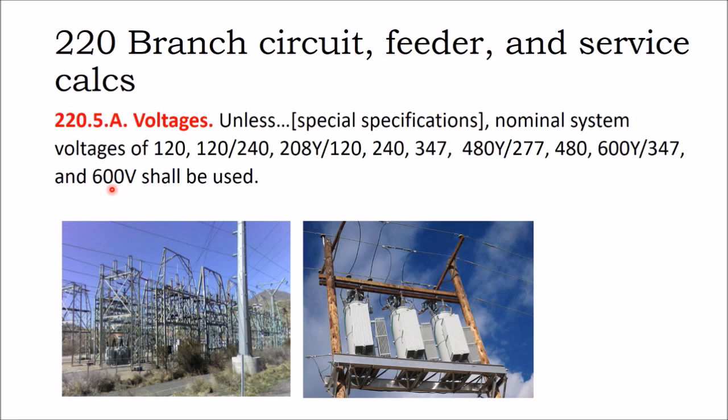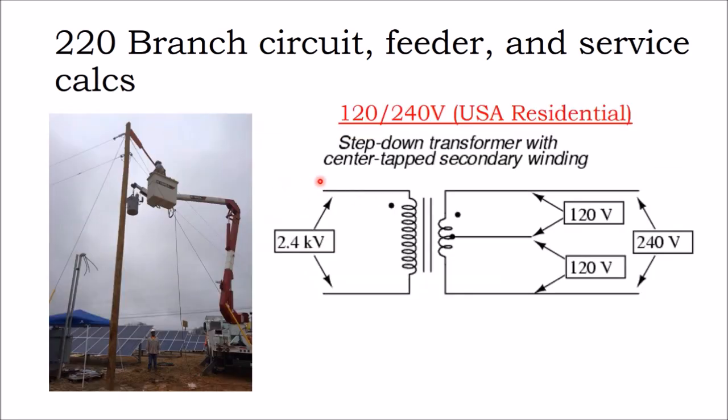I think there's an argument to be made for residential ground mounts of hanging the inverter on the side of the building and doing a lengthy underground conduit run using DC wiring. And for that matter, maybe the SolarEdge optimizers on a ground mount that step the voltage up to the top of its voltage range have some application, or at least string level optimizers in ground mount services for that matter.